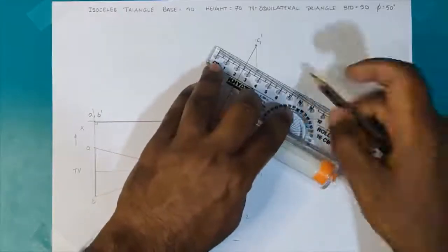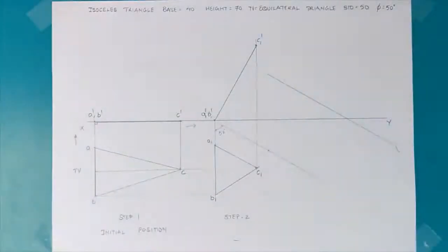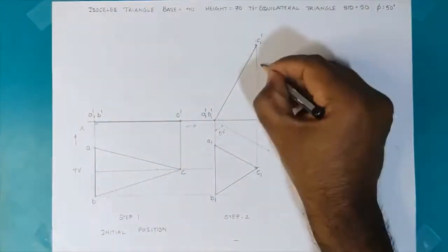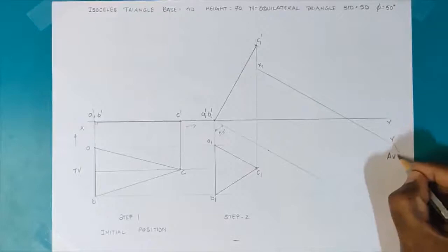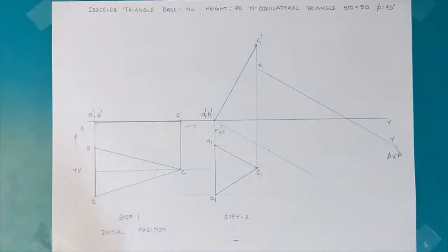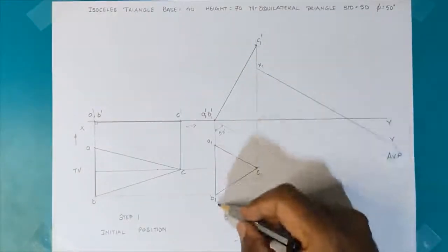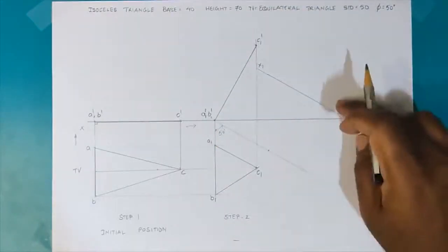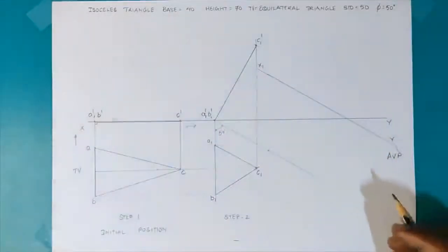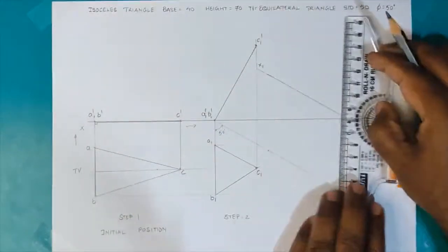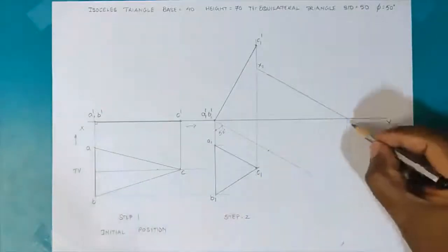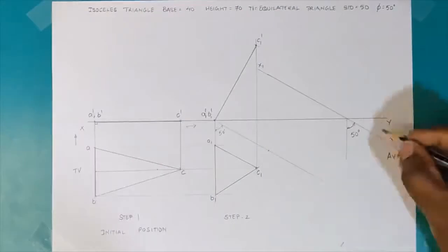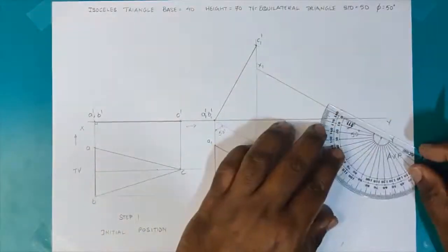So I take it further away, and then I'll find the auxiliary front view on this new auxiliary vertical plane. So I need to draw perpendicular projectors onto the auxiliary plane. So I need to construct a vertical. Before that, the angle I am showing is 50 degrees to the base edge A1, B1.